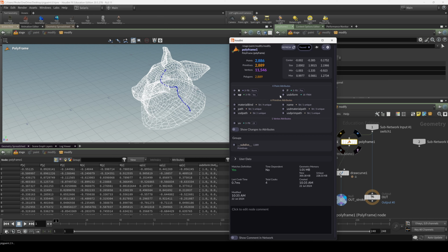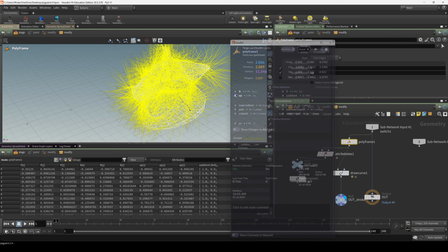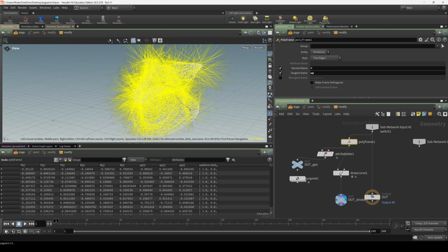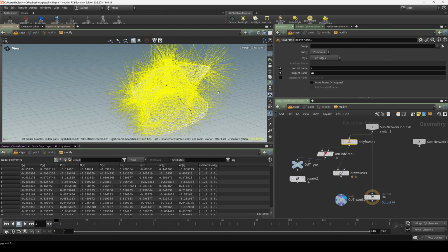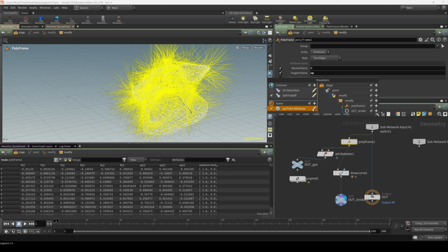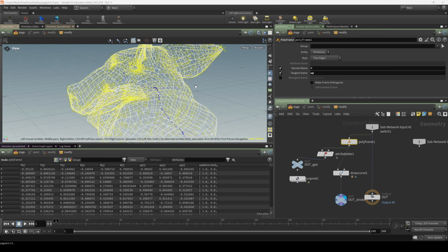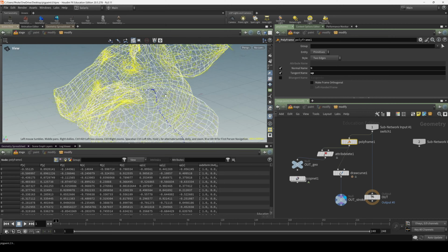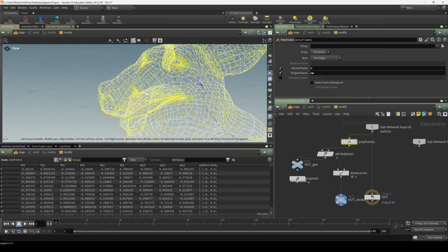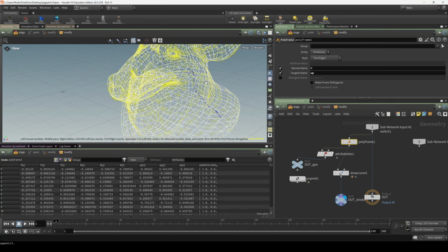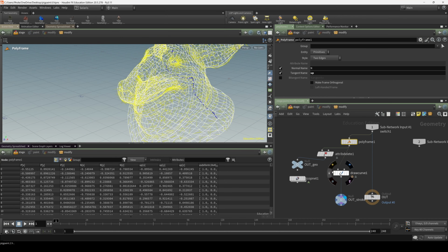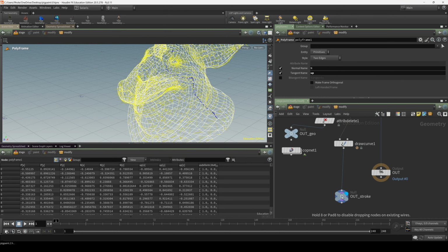The new view of attributes is amazing inside of Houdini. And the vectors here are way too long. So let's shorten those a bit here. We'll adjust our length scale so you can see what we've got. So here's my ups, and they're aligned with the surface, which is wonderful because we need that, our curve orientations relative to that.